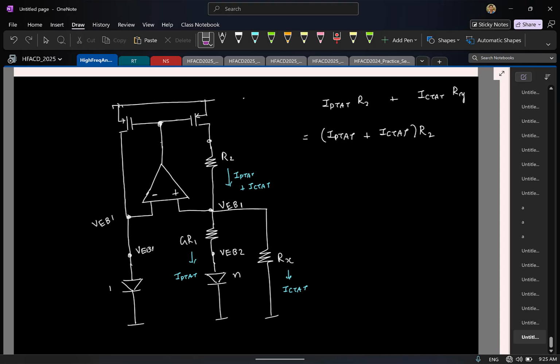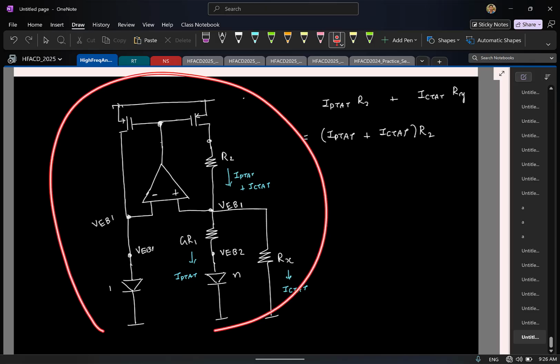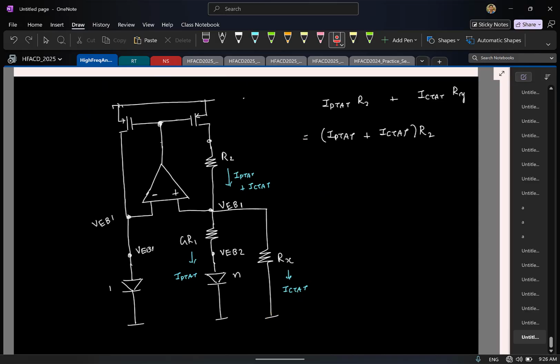So now let us say, taking a differential output is not, in the sense, a reference. I want a single-ended reference. So let us say I don't want to define this as my output, I want to get a single-ended output. So I have a current here, that is the required quantity. All I need to do is pass it through a resistor and take the voltage across it. So can you suggest some modification I can do so that I can take the output as a single-ended quantity?